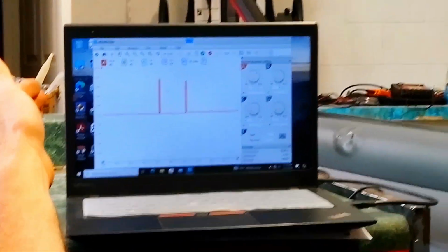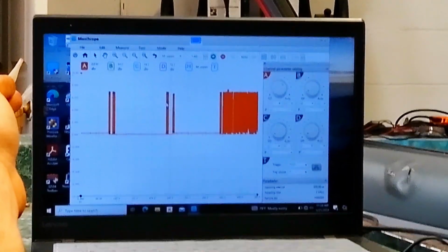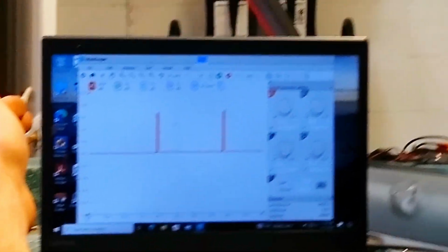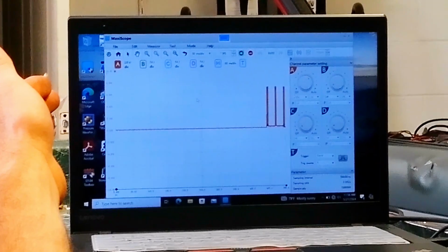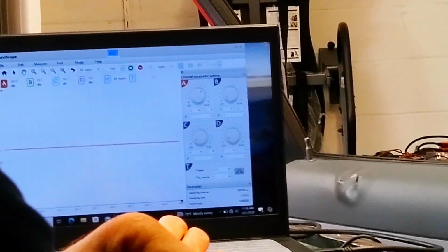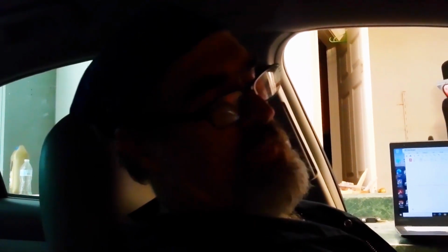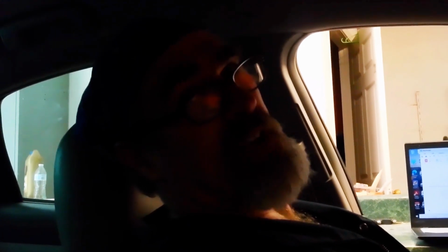And if you can see my lab scope running here, I'm going to turn the ignition key off and back on. You can see a bunch of network activity. We do have 7 volt square pulses just like we expect. Everything really looks pretty normal on this. So the next step we need to do, since we have heating and air conditioning no communication faults, is check our communication wire between that splice pack and the back of this module.